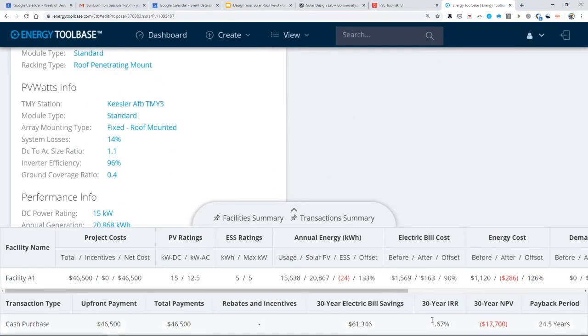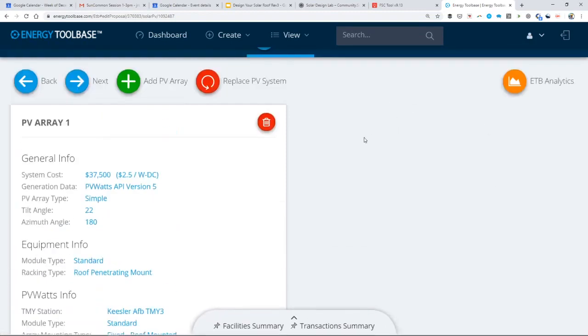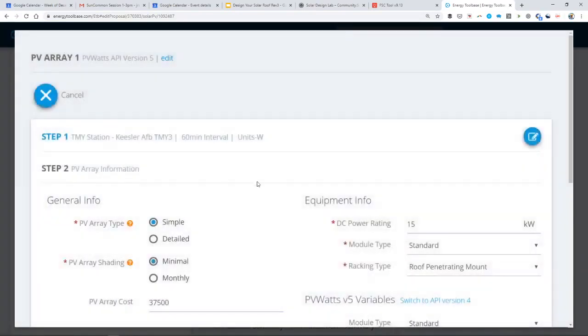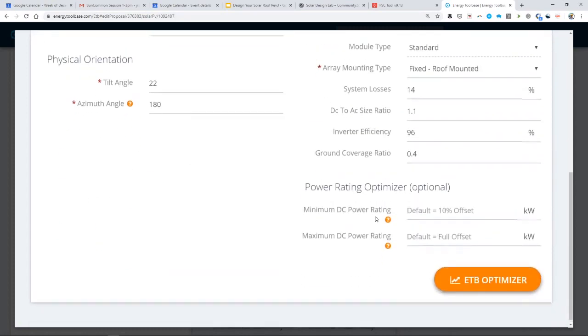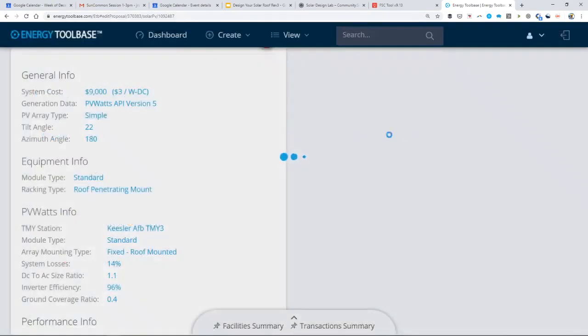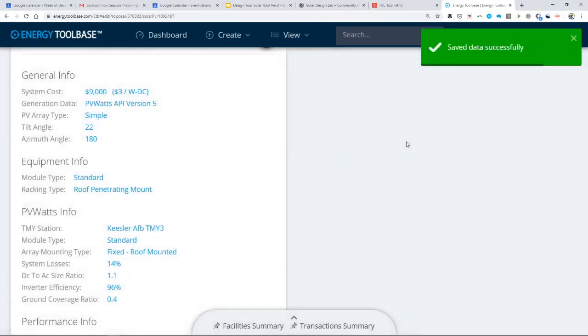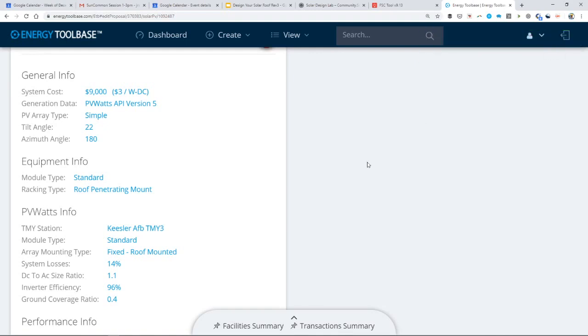And so now we go and see that the payback's 24 and a half years instead of 13 and a half. So, even though we got them a lower price on a larger install, because most of that is outflow, it's not worth anything, and so we have to only do little tiny solar arrays in Mississippi in order for them to be cost effective. Unless we take the whole house completely off grid. That's another class for another time.